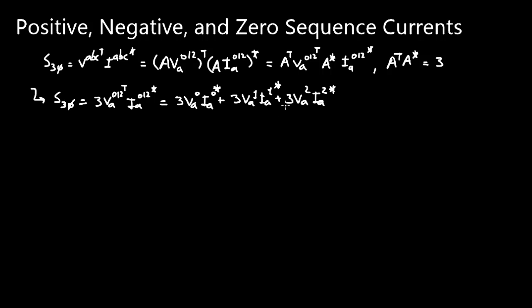Now, one more thing to note here is that I'm using the A phase on all the sequence components. So for the zero, positive, and negative sequence components, I'm just using the A phase current. Now, in practical applications, you would almost always see in industry that the A phase subscript is ignored. In other words, when you talk about the zero sequence current, you just say I0, and when you talk about the positive sequence, you just say I1, and for the negative sequence, you just say I2.